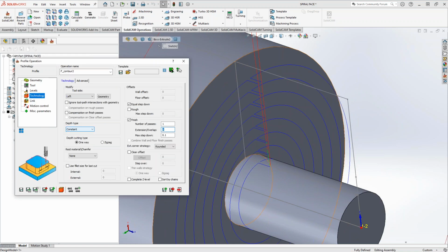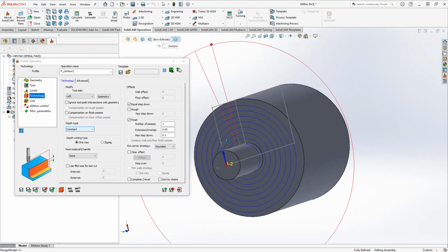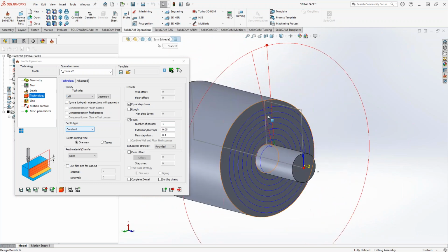So if I'm worried about that little gap there, even though this represents the center of the tool, and the angle that the tool is taking probably is actually overlapping there, just to account for that, let's put in a 50 thou. And that kind of just closes that up a little bit, eliminates that witness line that's being developed there. So that's one way to do this, but it's fine. It might actually leave some witness lines around there and some rings in concentricity. So maybe not like a witness line, but a witness ring, if you will.